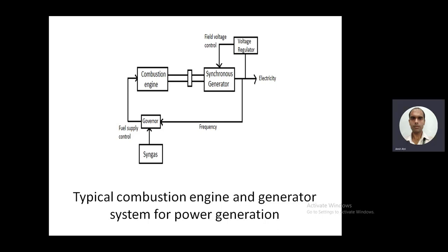So any change in the power demand, like the load increasing, makes the system frequency decrease, and if the load decreases, the system frequency increases. So, to maintain the system frequency constant, we have to correspondingly change the generation. Like, if the load is decreasing, we have to decrease the power generation.